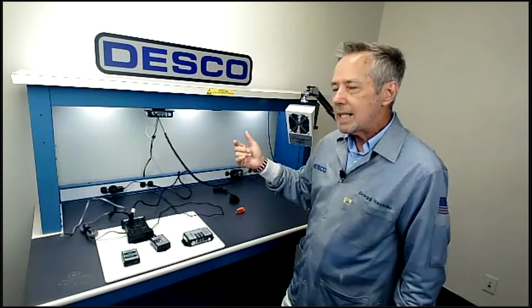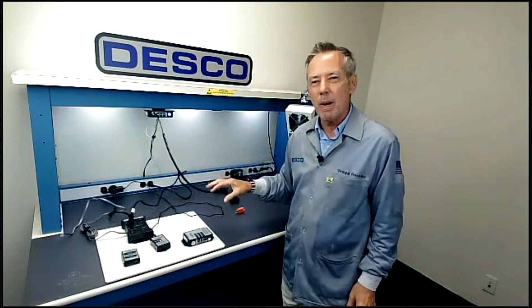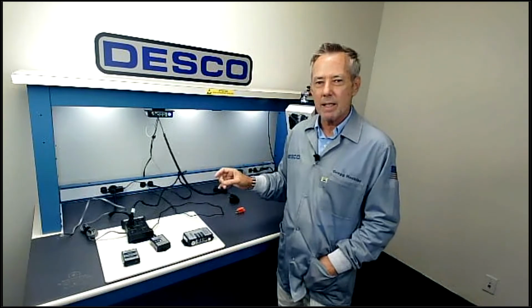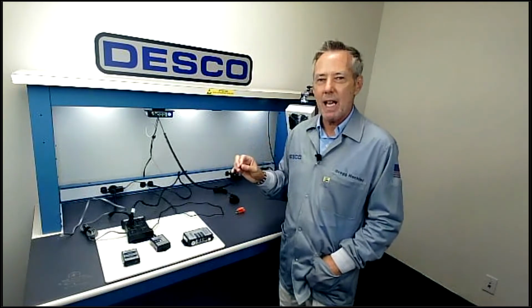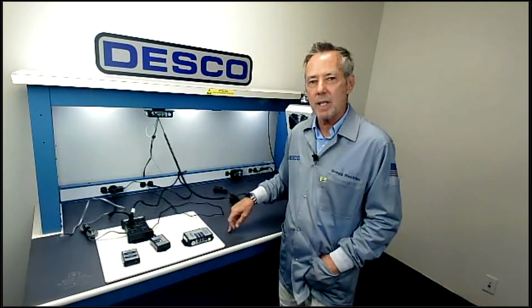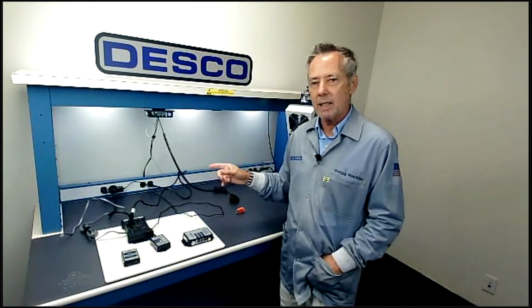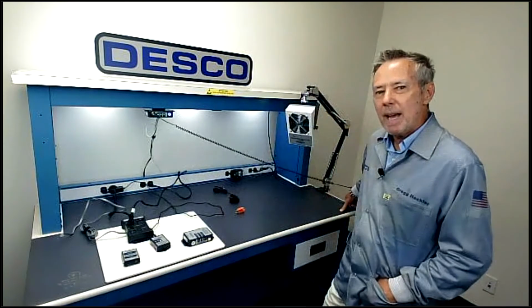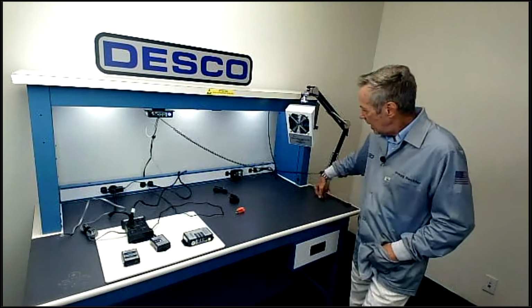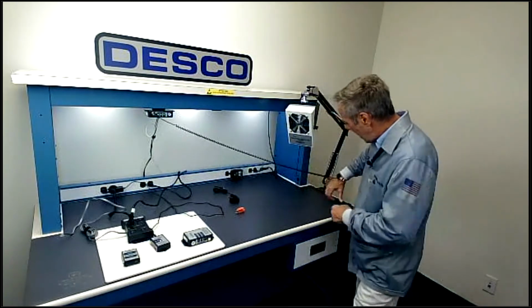The other thing, as I mentioned before, is that all three of these monitors monitor ESD work surface connections. I want to emphasize that continuous monitors do not monitor the surface resistance of your work surface. They monitor the ground connections. Over here on the left side of my mat, I have my ESD ground, and on the back, I have my monitor ground.